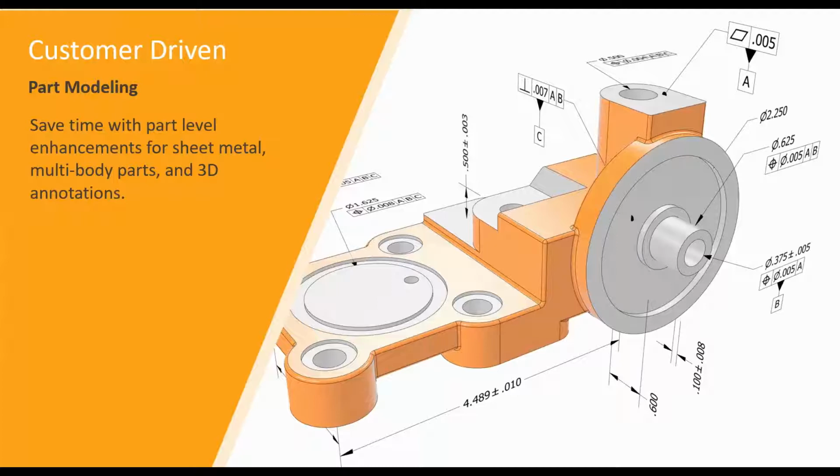So majorly, there has been a reduction in the number of mouse clicks for familiar window selection for selecting multiple bodies and faces in your parts. The unwrap command gets even quicker with additional options for constraining planar holes and alignments of the unwrapped surface. The sheet metal flange angles can now refer to existing edges and faces for the specified angle, to maintain associativity really between two environments.